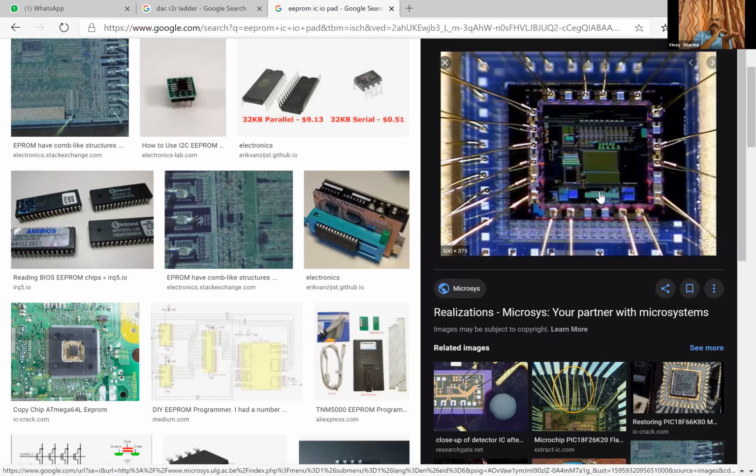So generally you don't put a single layer of metal, but you put all the metal layers beneath. So generally on the IO pad, you have metal 1, 2, 3, 4, 5, 6, 7, 8, or all the layers which are used in your fabrication process, all the layers, okay? So if you see a cross section of an IO pad, you should see all the layers of metal, okay?